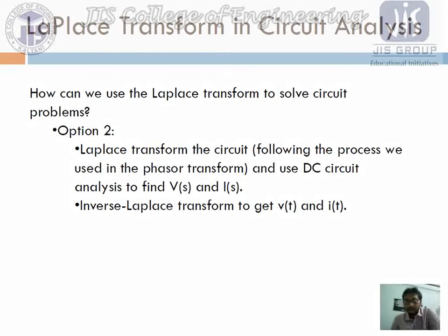And similarly for option 2, at the very first, we are applying the concept of Laplace, or similarly we are transferring all the quantities available within the circuit into the S domain, and then again we are applying KCL or KVL, and then we are applying inverse Laplace to get the actual equation, right?